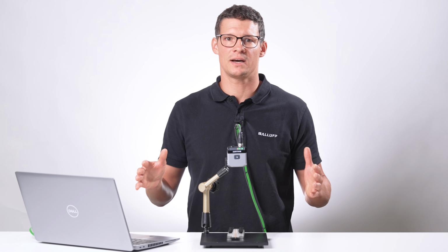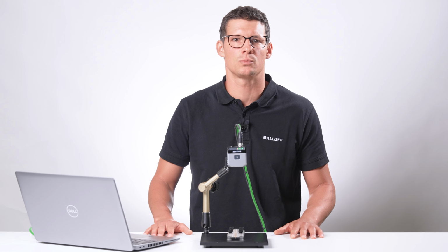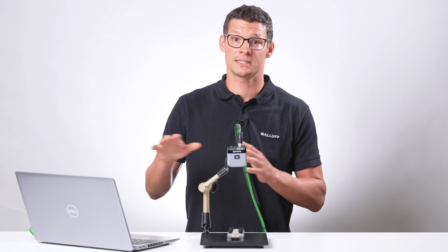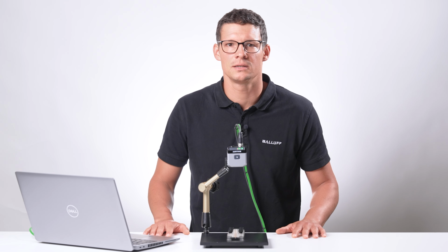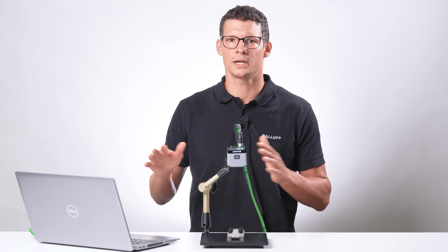The locator works with an edge model, so it is important to select regions with many edges and high contrast. It's also advisable to be careful with rotationally symmetric parts and parts that occur more than once in your image, because this can lead to unwanted effects. Now you have a better understanding of image processing and we can have a look at the locator settings.